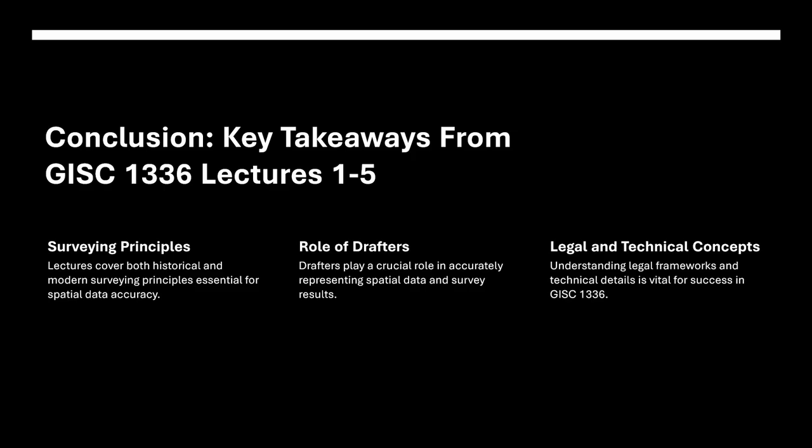In Lecture 4, we turned to plats. We learned that a plat is not simply a picture. It is a legal instrument that speaks for the surveyor. Title blocks, bases of bearing, closure statements, monuments, adjoiners, easements, legends, certification, all of these are not just formalities. These are pieces of a legal record that may be read in the courtroom, relied upon in a deed, or used to resolve disputes long after we're gone.